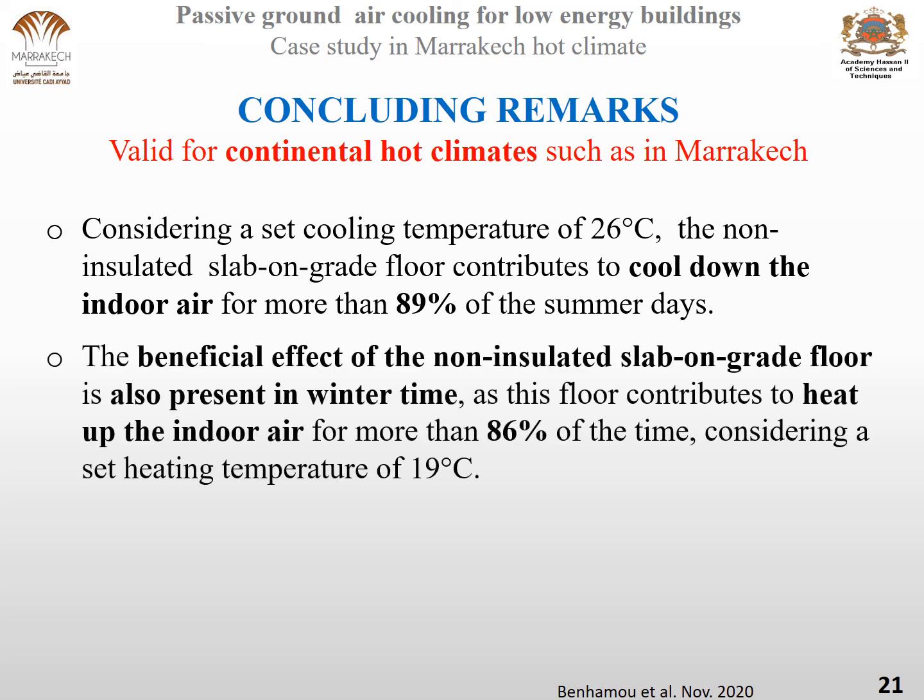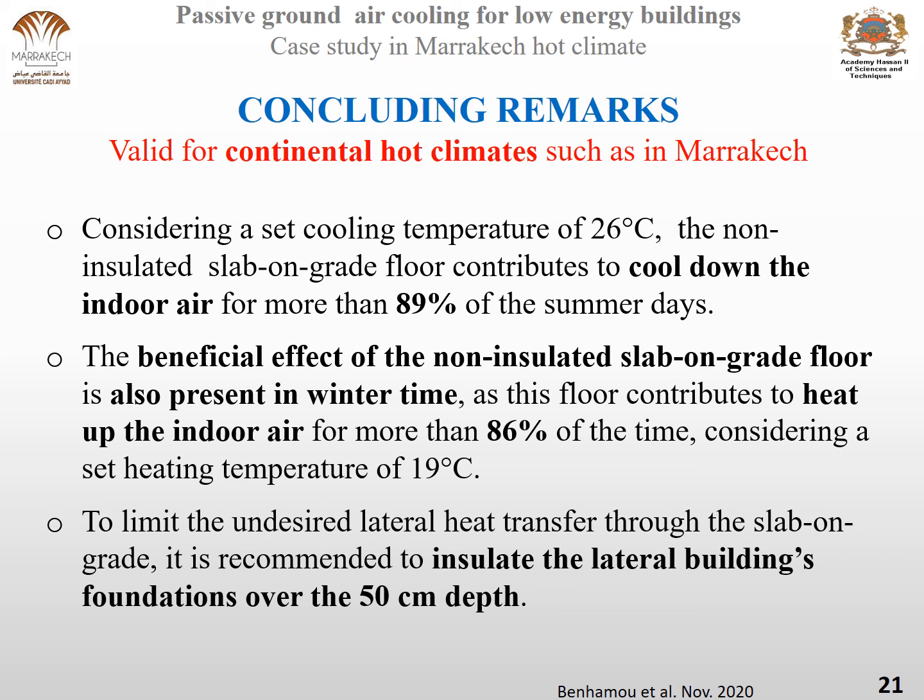Also, the beneficial effect of the non-insulated slab-on-grade floor is present in wintertime, as this floor contributes to heat up the indoor air for more than 86% of the time, considering a set heating temperature of 19 degrees C. Furthermore, to limit the undesired lateral heat transfer through the slab-on-grade, it is recommended to insulate the lateral building's foundation over the 50 centimeter depth.